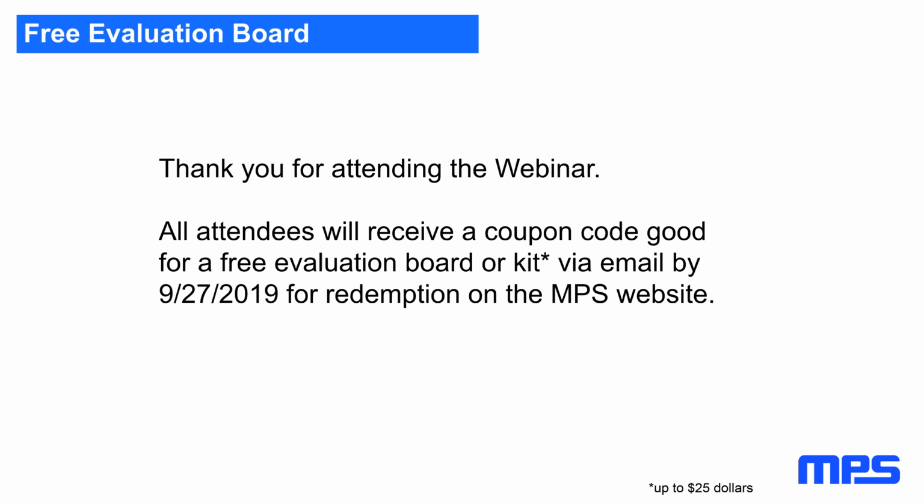So you will be surprised how big the differences are between a SPICE simulation, as I showed you, and a real measurement. So go ahead and measure them with a vector network analyzer, and you get a really good feel for it. It's not as easy as you think to get good damping. But typically for the high frequency, it's more a matter of parasitics.